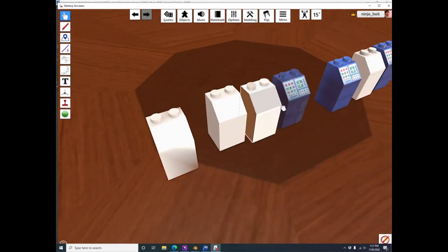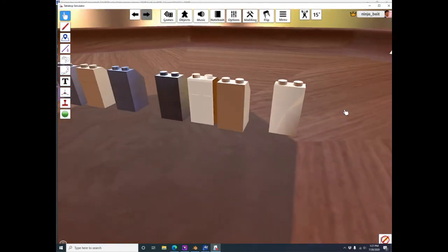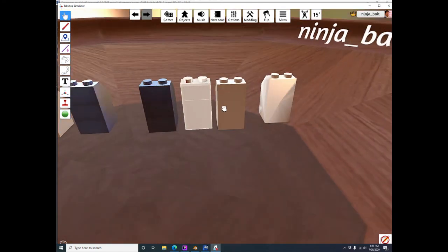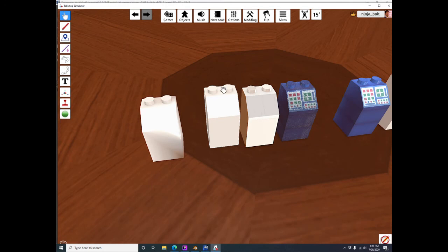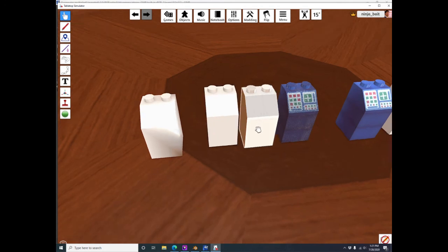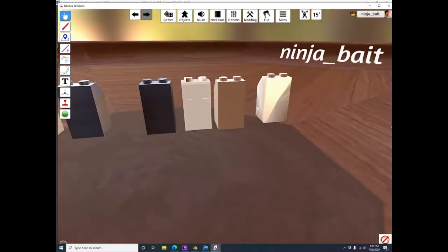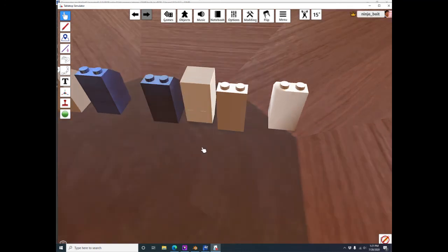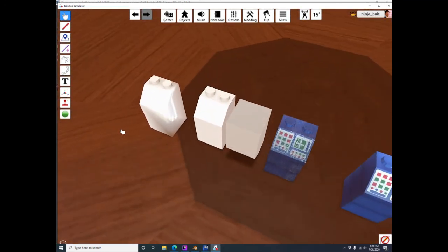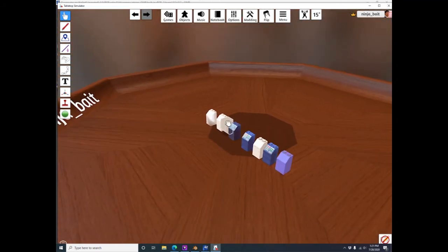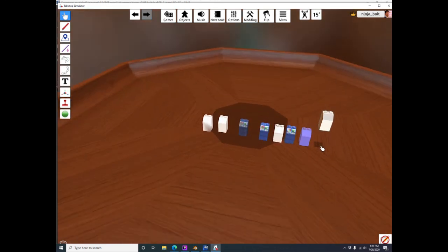But you can see that the decoration, the decal, has a little bit of an edge to it. And you can see that there's some weird shading going on around the cylinders. And that's because we didn't match the number of faces on the studs exactly. So this might actually be a case where we don't want the normal map because it just doesn't look like it's adding a lot. But there are cases where you will actually see that it adds a lot for grills or ridged bricks. So let's leave it out.